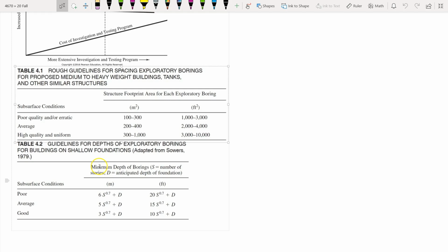And the final question: SPT or CPT? The common practice now is, if you can, it's better to include both. We understand CPT is cheaper and quicker, but SPT has an advantage that CPT cannot replace, which is being able to collect soil samples.